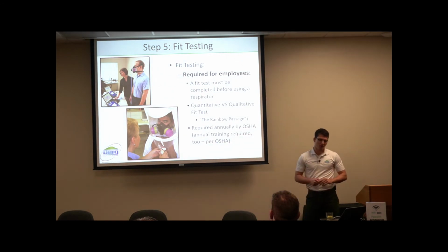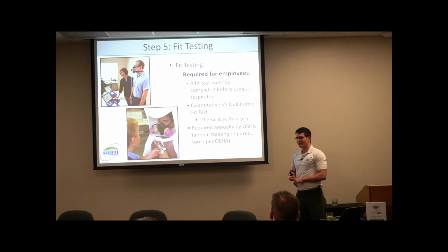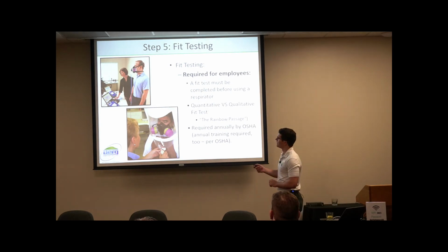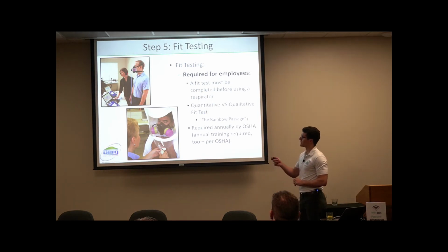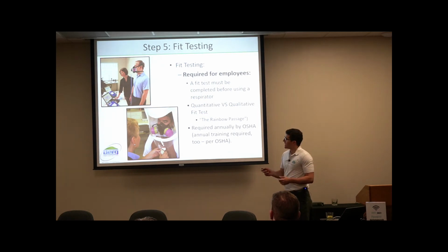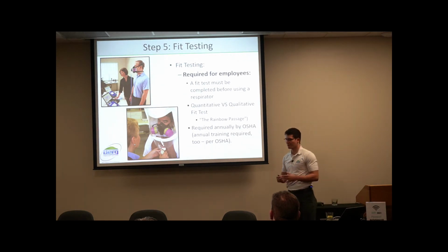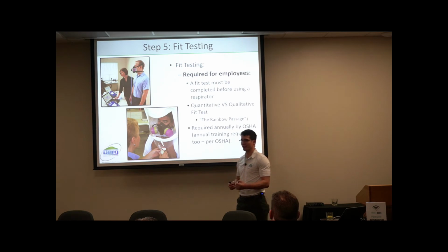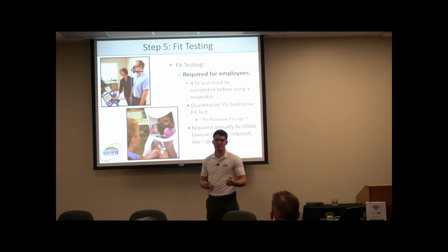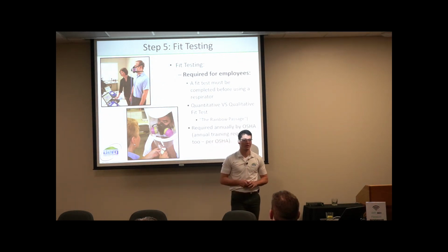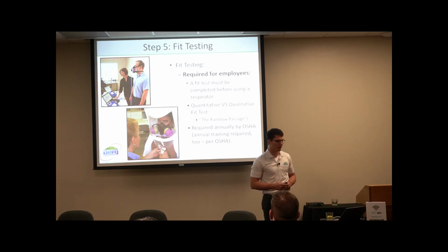Okay, so there's a difference between a quantitative and a qualitative fit test. Quantitative is up on the top there, and then qualitative down low, where it's more of a subjective measurement: do you smell it? Do you not smell it? Yes or no? And on the top, they actually hook up a measuring device to see what concentration has intruded into the inside of that respirator. Okay.